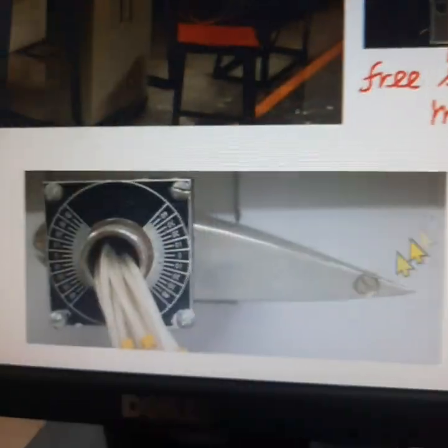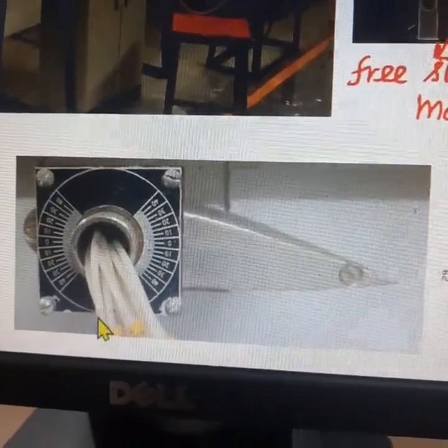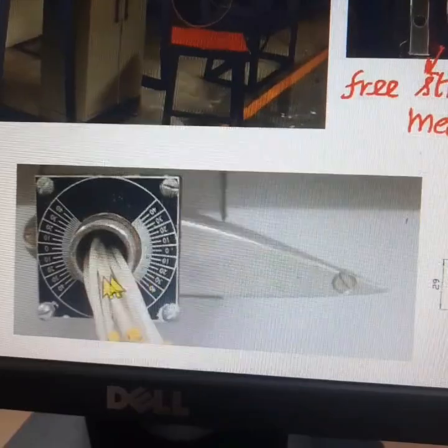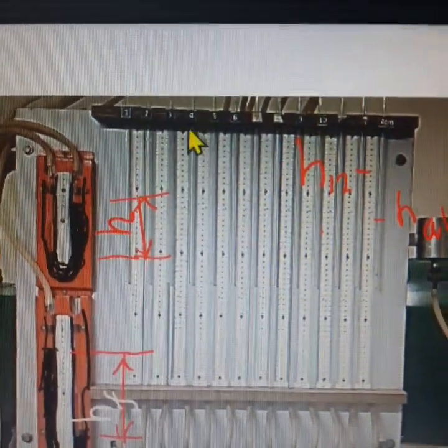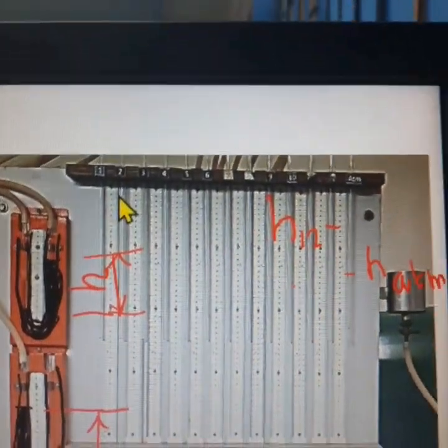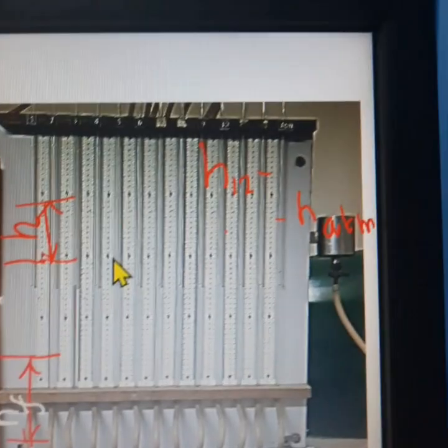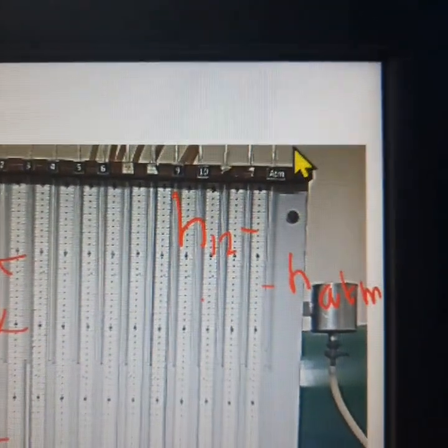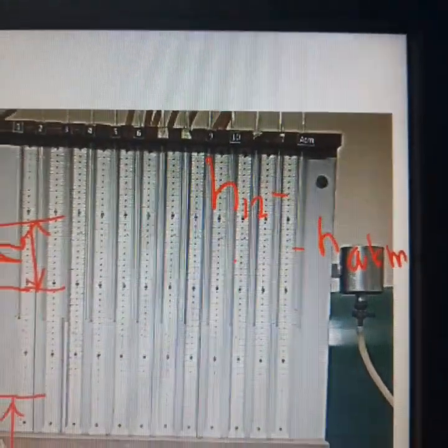These 12 pressure tapping points are connected to the manometer bank using hoses. The tubes connected to the pressure tapping points are taken to the manometer bank, which has 12 manometers on this setup. The last manometer is open to atmosphere, which records the atmospheric pressure.